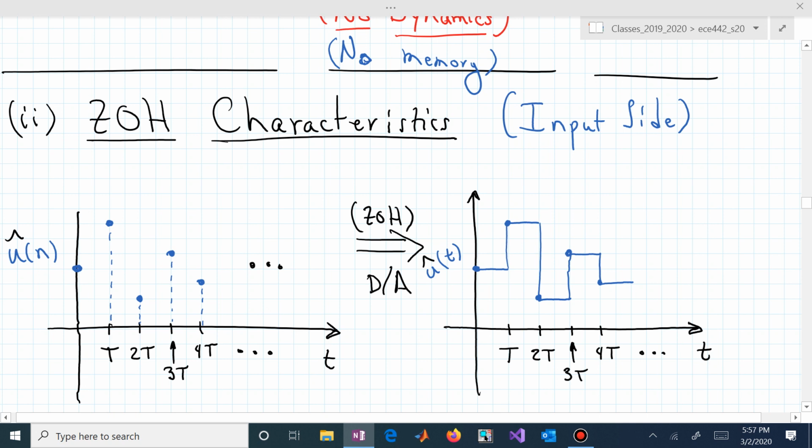Our plant is an analog plant. It cannot respond if you took a DC motor and applied to that at time 0, 2, and then at time 0.001, which is the next sample period, you said 2.1, and you just did 2 and then quit, and then you said 2.1, it's going to go, what is going on? It won't respond. It needs an analog waveform. We are now making that happen by simply holding that constant in between sample periods.